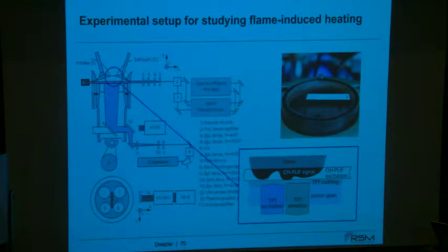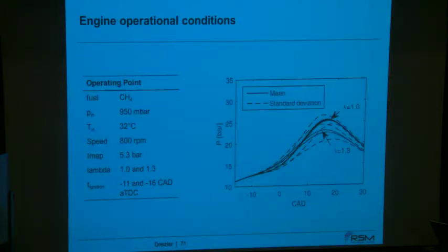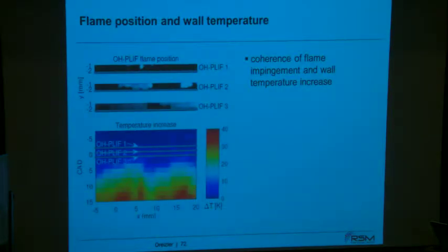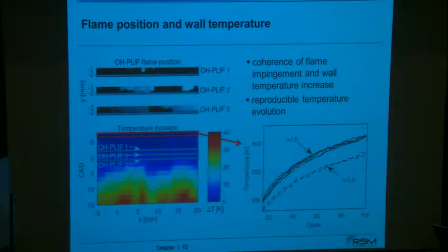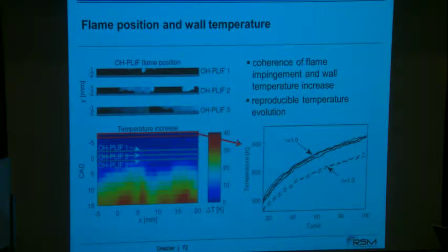You can calculate that in the paper we just published, which is online now in Applied Physics B. We calculated as well the heat transfer with a 1D model, and by assuming certain properties for the phosphor coating, it could explain this phase lag, I think, in a correct way. When we're doing that and compare different cycles, here you see the cycles that have been recorded after the heat up. This was motored, fired, and then finally taking the data.